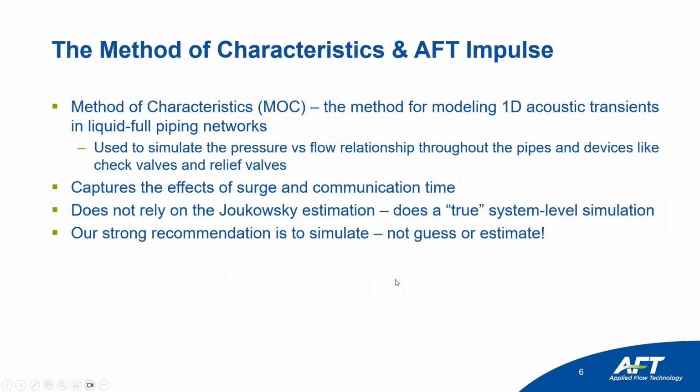Again, the method of characteristics is a system-level tool for simulating 1D acoustic wave propagation in liquid-full piping networks. It's what Impulse uses. It captures the effects of surge and communication time really well. It's industry standard and has been for decades. And again, it's not using this Joukowsky estimation. We're just referring to that as a ballpark figure.